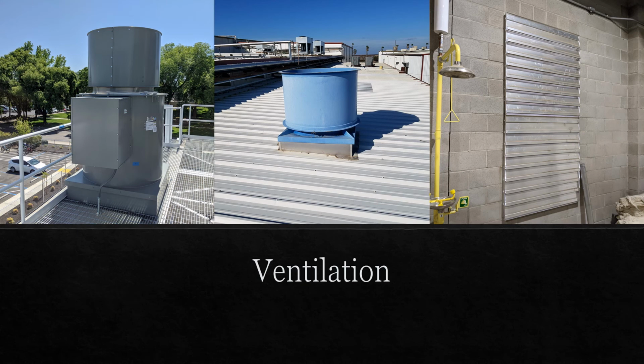At minimum, existing machinery rooms must be provided with occupancy ventilation and emergency ventilation. IIAR 9 does not specify the required ventilation airflow rates, but rather requires compliance with the codes and standards in effect at the time of construction or modification to the machinery room.